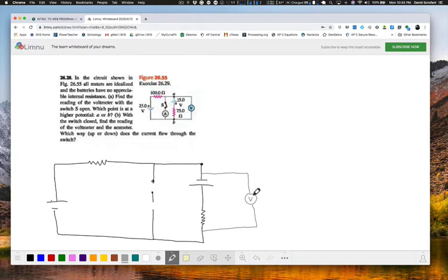All right, and I think right off the bat that's going to confuse a lot of people that are trying to do this problem when they see this path over here drawn as it is in the circuit. So let me go ahead and make that point right there. Okay, I'll put the ammeter in right there. Ammeters, by the way, have very little resistance. Voltmeters have a lot of resistance, so they don't draw much current, so very little current follows this path. You can assume no current, in fact, for the sake of the circuit solution.